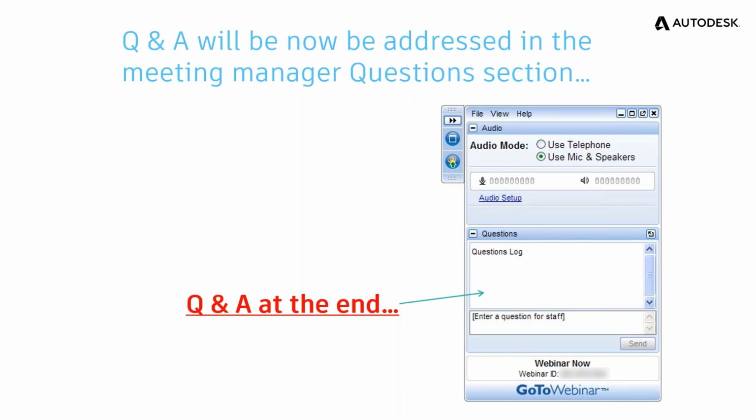Do you use scripts to create or customize blocks? You can. That's not what Dynamic Blocks is doing, but you can incorporate some scripts for very unique niche situations. It is not something that's done routinely, but it is a capability that's there.